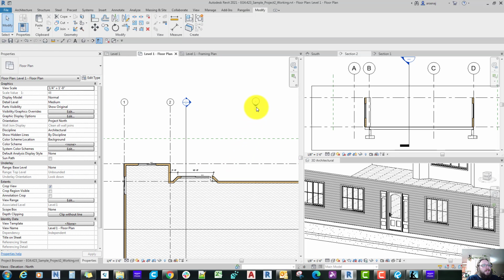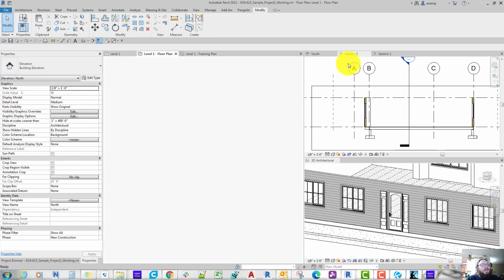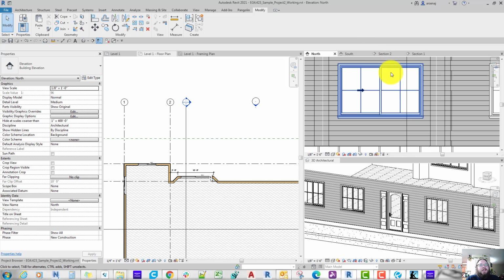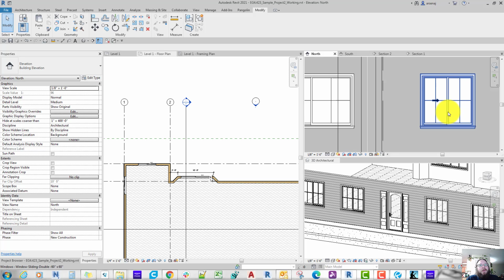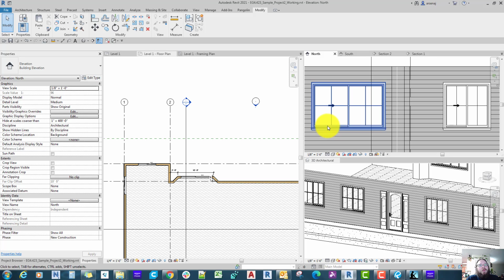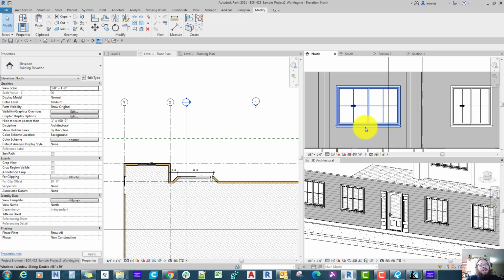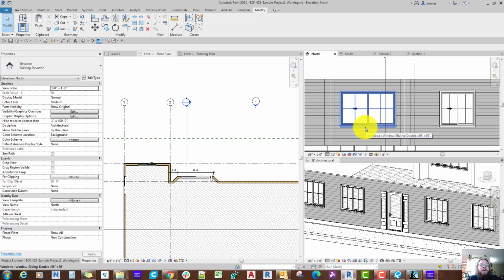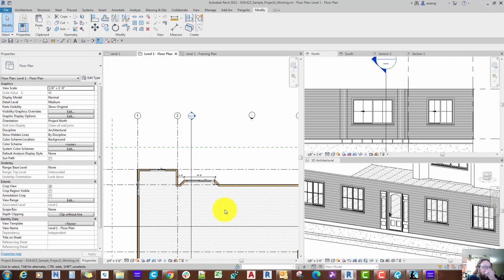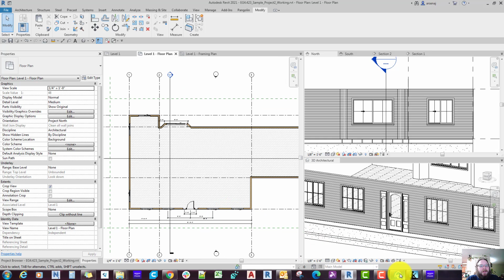Now if we look at the elevation on this side, we can see the family automatically updated the window, and it stretched it out and made this all equal. See how it was originally? In the family there are parameters that control where these window mullions are, and so it just made it wider. We can come back later and add some additional detail or even change the window out completely, but getting the families in as a placeholder is a good place to start. So we got that window in. Let's go look and see what else we have in around this footprint.